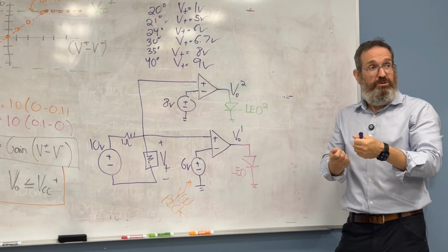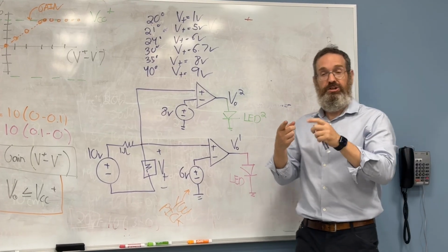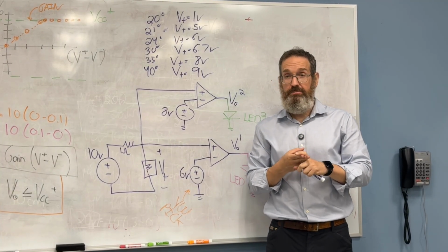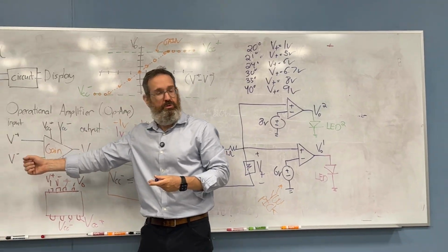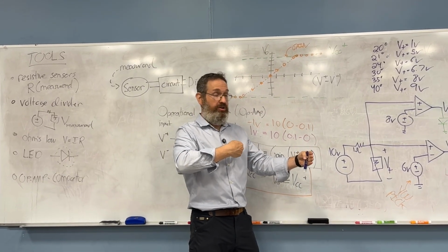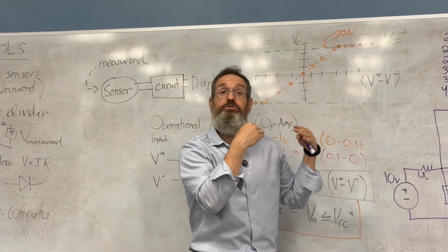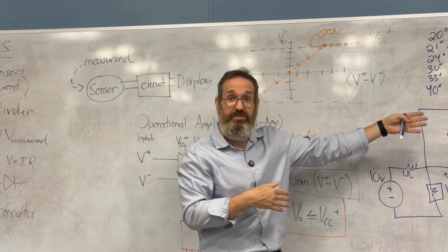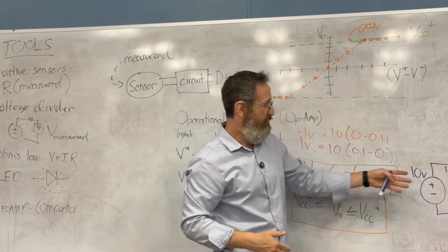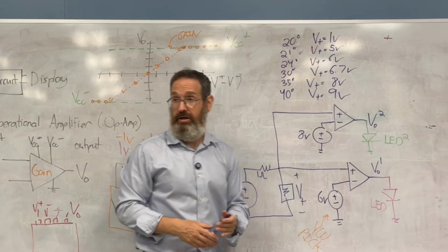So now you can make an instrument where the lights go on and off whenever you want. You need the equation for your sensor, and you need the equation for your circuit. If we go back to the other example that started with the motion sensor, and I said you have to make it so that when it goes from 0 to 10 centimeters, a blue light goes on when it crosses 5 centimeters, you could actually figure it out. You have to think it through a little bit, but as they cross 5 centimeters, the voltage crosses a certain point, and that's when you trip your comparator.